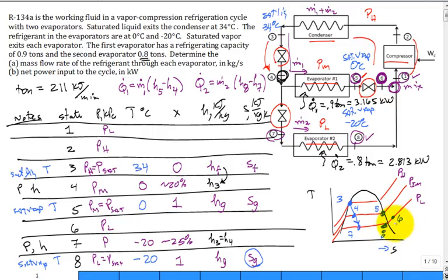So you have to work on it. I know it's probably, I said it too fast. So you're just checking the tables? Checking the tables, yeah. We have two pieces of information at fixed state 6. What again are they? Enthalpy. Oh, I didn't write it down, did I? It's the pressure and the enthalpy that fixed state 6. It's isenthalpic. So H6 is equal to H5.